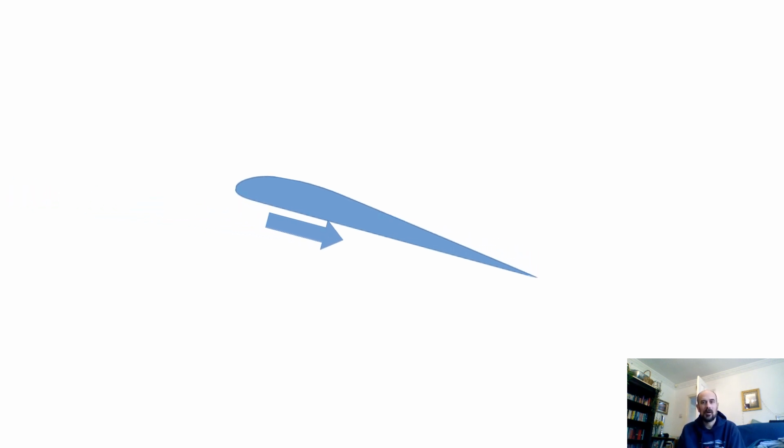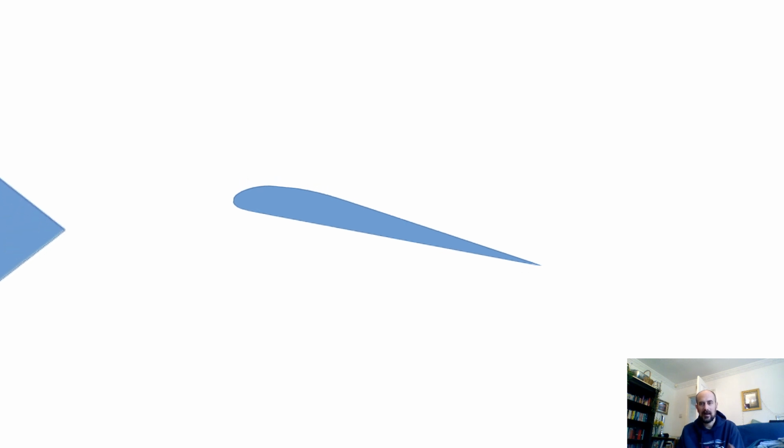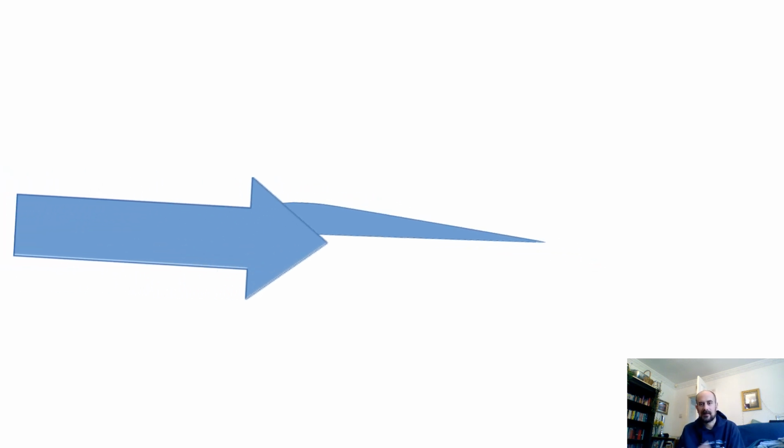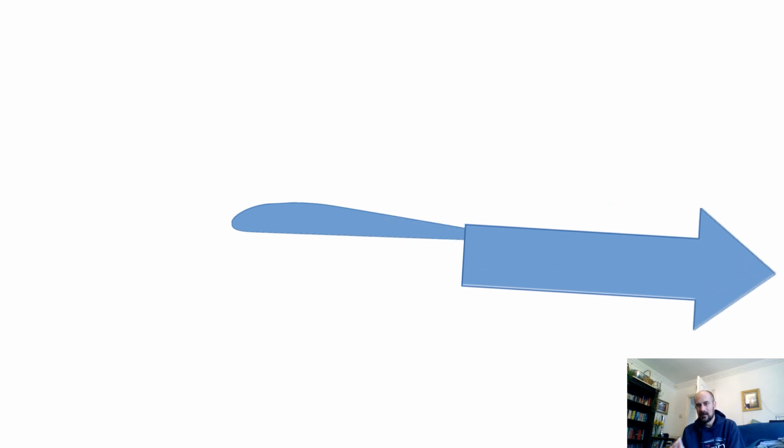It's deflecting the air through the angle, working the air, that creates the drag. So if we want to create a certain amount of lift, and we do, then we have two choices about how we do that. Either we can take a relatively small amount of air and shift it through a very big angle, so push down really hard on a small amount of air, or we can take a large amount of air and push down on it more gently so the angle changes by less. The second one will produce less induced drag because the angle that you're shifting the air through is lower.